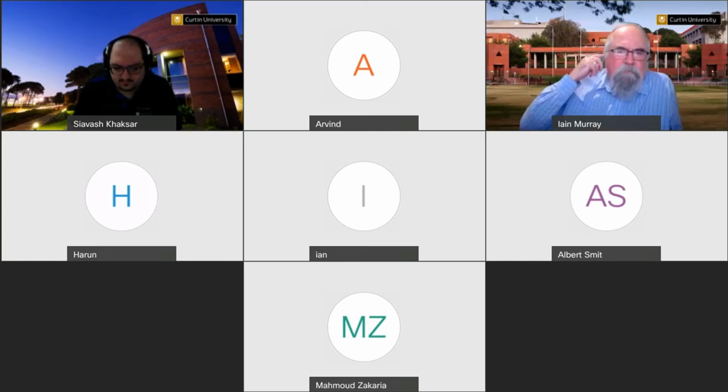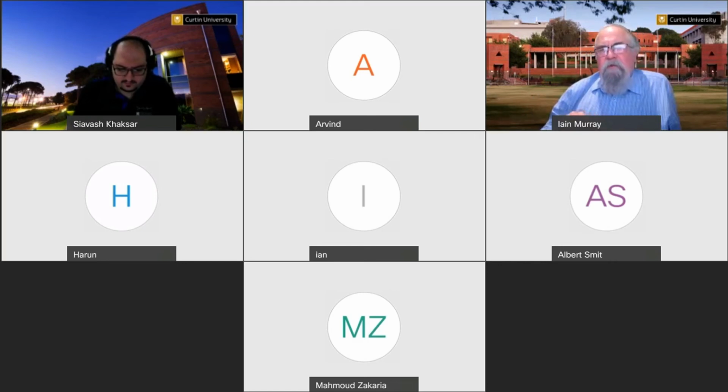So what you could do is have the microphone on the fingertip picking up the click, but additionally have other microphones that pick up the surrounding noise, away from the fingertip. You then subtract that external signal, after normalizing them to the same level, from the signal you're getting from the fingertip microphone. That way you should end up with the majority of your signal being the click from that fingertip. Then it's a question of identifying what that click is like.